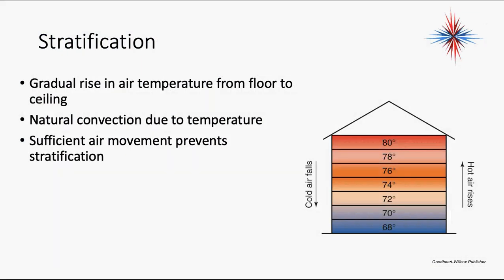Stratification occurs in every house. That's what I was just showing you in those other pictures. It's a gradual rise in air temperature from floor to ceiling. It's natural convection due to temperature. Sufficient air movement prevents stratification. If you're standing in a room without any air movement whatsoever, the temperature near the ceiling is going to be much higher than the temperature near the floor. Now, sometimes that's a good thing.